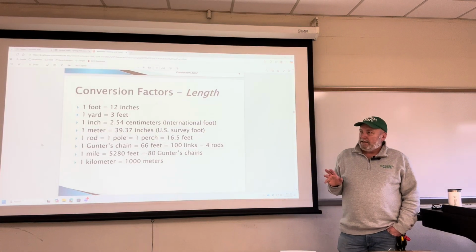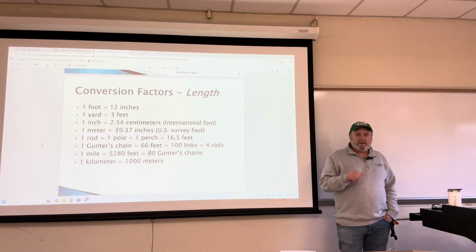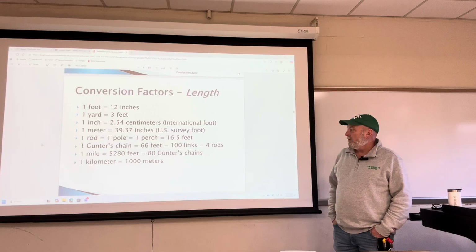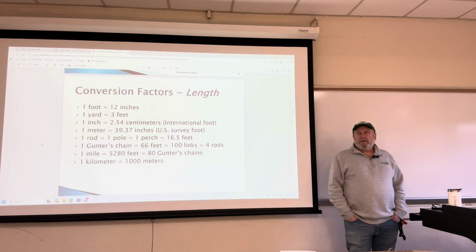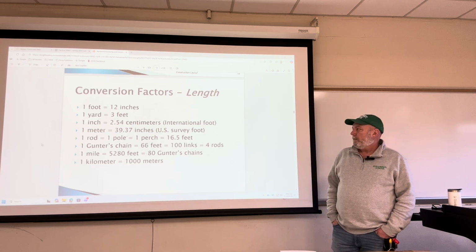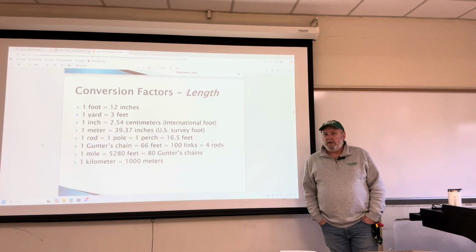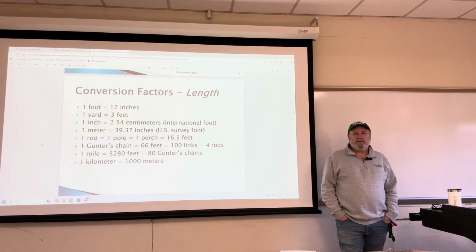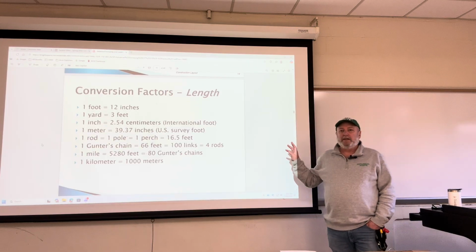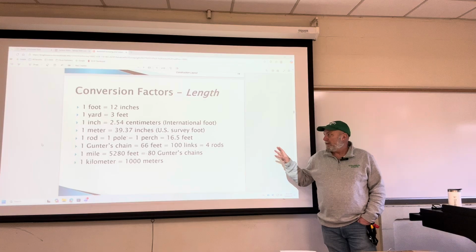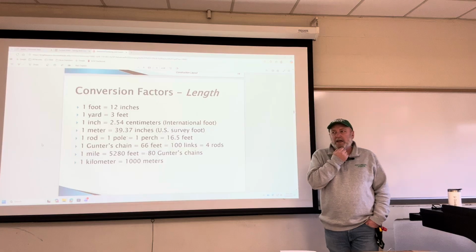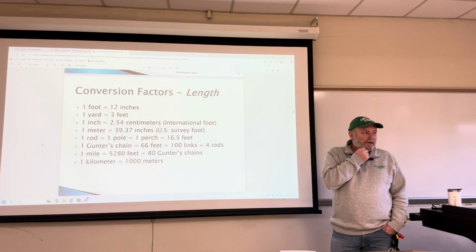There is kind of, at this time, 2 feet in America. There's the U.S. survey foot and the international foot. I want to say it was December 31st, 1922, or 2022, the U.S. survey foot was officially retired and not used. We are to be using the international foot. That's going to change this year, most likely, where everybody's going to have to go to the international foot, because of some geodesy type things. We're getting our datums modernized.